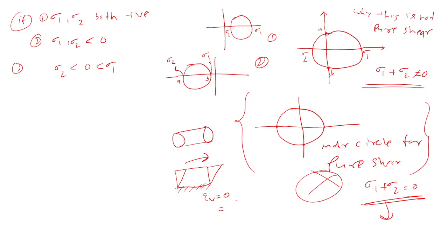Epsilon x plus epsilon y plus epsilon z. Okay, that is there. But when we add all those, it will become sigma x plus sigma y plus sigma z, times 1 minus 2 mu, divided by E. It is correct, right?